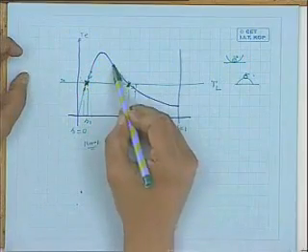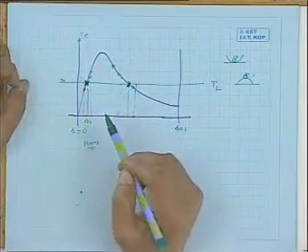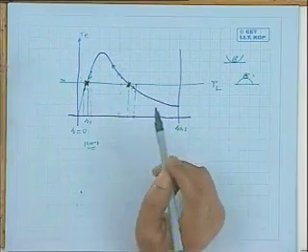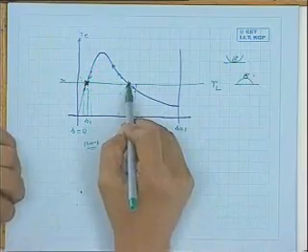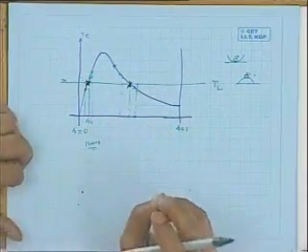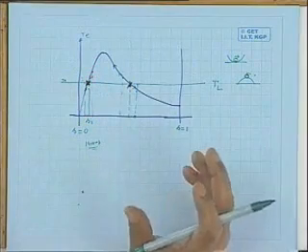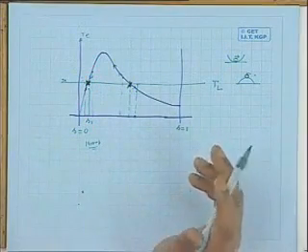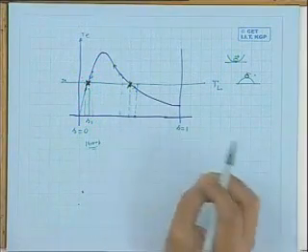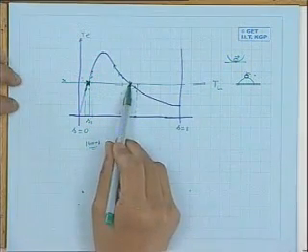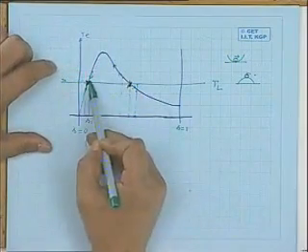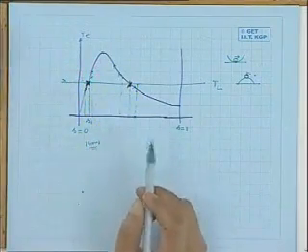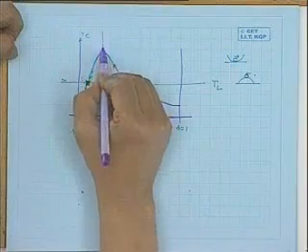And of course, in this way, if a disturbance comes in this direction, then the machine will finally come to this point and settle down. Therefore, you find that although it is theoretically possible to operate the machine at these points, practically it serves no purpose, because a slight disturbance this way or that way will either make the machine come to a stop, or bring the machine to a higher speed like this.